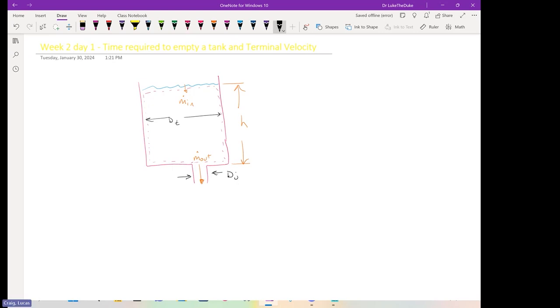Okay, so control volume. Control volumes are this dotted line. They represent a boundary that changes. When we do thermodynamics, this room, if we close all the doors and we have an imaginary boundary in it, with the doors shut, nothing can go in and out of the boundary, so it's a closed system. Here we have an open system because we have water leaving.